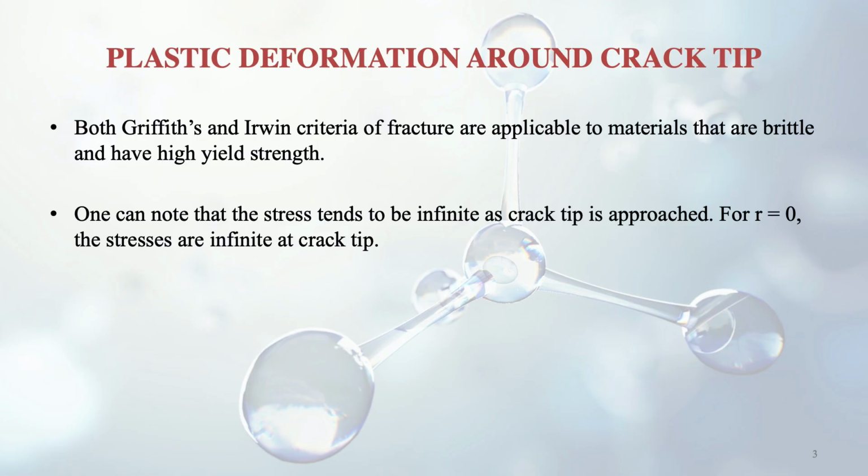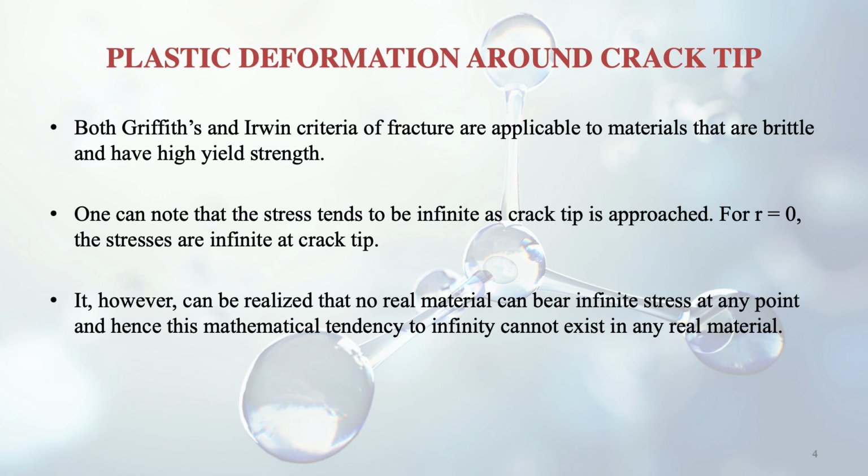For r equal to 0, the stresses are infinite at the crack tip, meaning that if the radius of curvature of that crack is 0, then the stresses will be infinite, because the area of cross section is almost 0, and since the area comes in the denominator, the stress becomes infinite. It however can be realized that no real material can bear infinite stress at any point, and hence this mathematical tendency to infinity cannot exist in any real material.